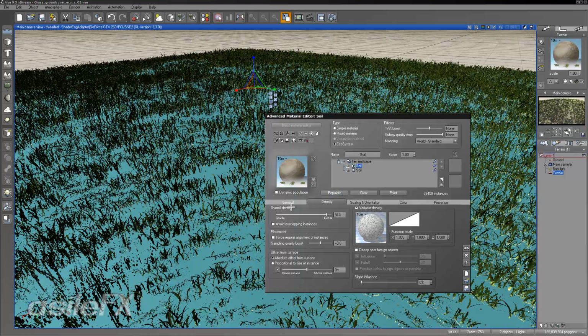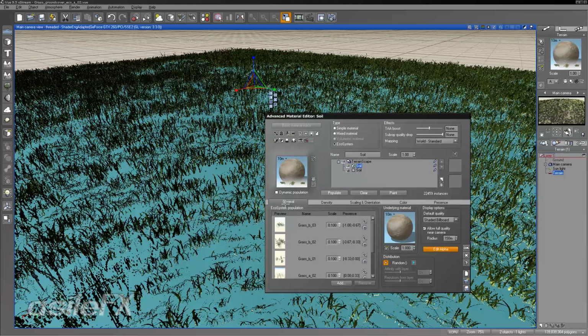If you have any version prior to 9, there is no alpha for ecosystems. Instead you use basically what I'm using right now, where you set the density to 0 within a function in order to remove the area. But you can set up a specific alpha, which is now separate from the density, to be able to remove areas of instances. It does make it a little bit easier. I do want to set up a slight scale change, just so there's a little more variation throughout.